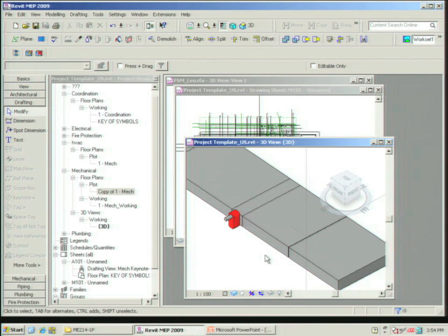But keep in mind that if you apply a filter, that object can still break. I'm saying in hidden line view setting, let's say your lighting fixtures are on top of the electrical and mechanical equipment, it's still going to have that break line because you're controlling by filter, not visibility graphic overrides. So I really do not recommend doing visibility graphic overrides unless you really have to.